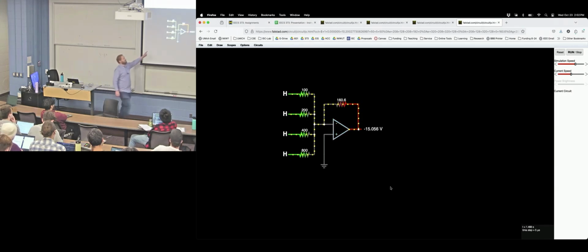The gain factor here of summing all those currents and then giving it some amplification, turning the current into voltage through that output resistor, gets you a value of 15. We could sit through and walk ourselves through those equations. The negative and positive op amp rails just tell you the maximum voltage or maximum negative voltage that it will produce. Okay.